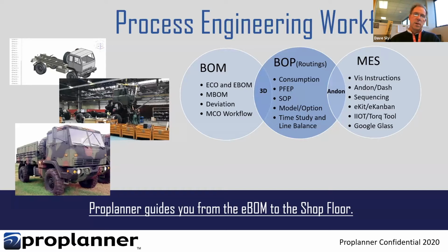We're also going to deal with not just the fact that there are 8 bolts, but which bolts are actually assembled at which time. So we're dealing with instances of items at certain times when they're needed, which is also part of the MBOM. And then the MCO workflow, the manufacturing change order, because every one engineering change order could be represented by multiple manufacturing change orders. It could trigger multiple manufacturing change orders, where change orders might relate to logistics problems or changing task locations on assembly lines or tooling changes.